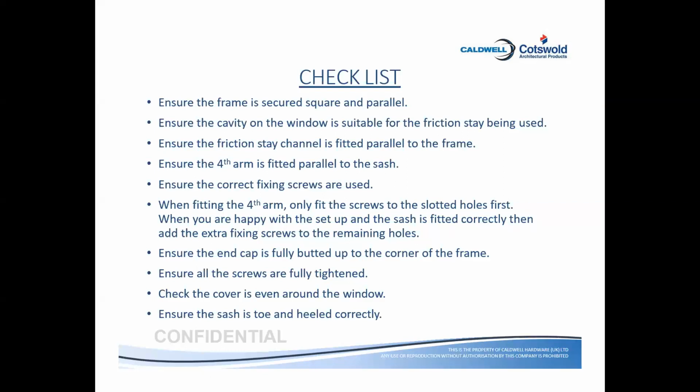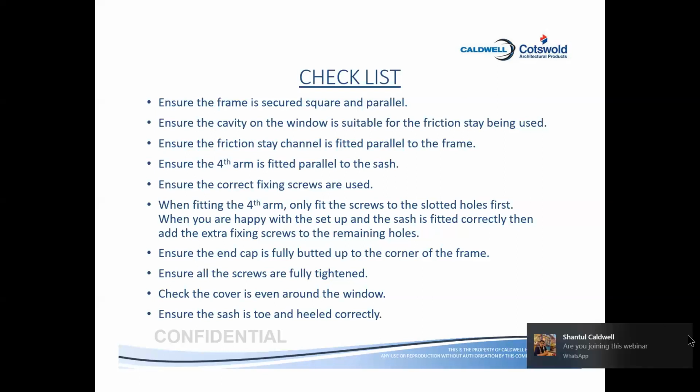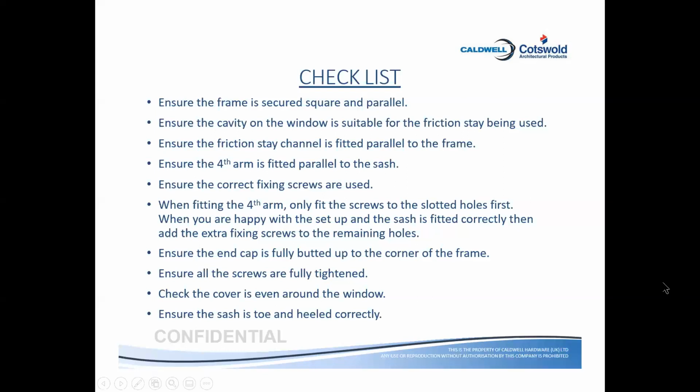If you use pan head where the arms are, there will be an interference with the head of that screw and the marking will be there, and eventually there will be a sound. That's why it's not suggested. We suggest to use CSK screws, 5 mm diameter, made of stainless steel 316 grade.